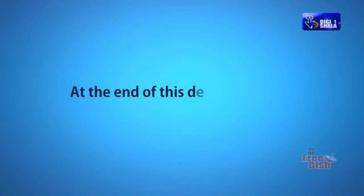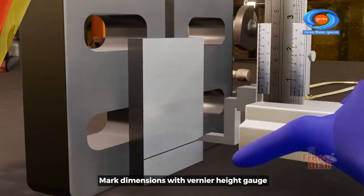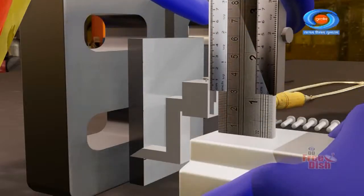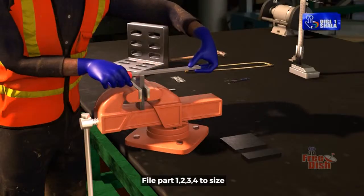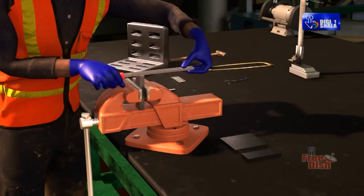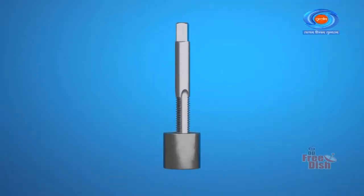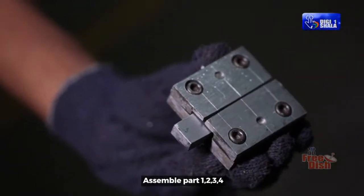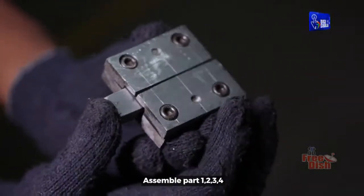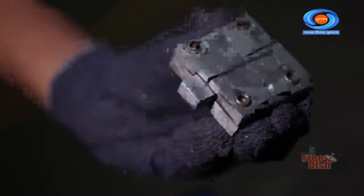At the end of this demonstration, you will be able to mark dimensions with a vernier height gauge, file parts 1, 2, 3, 4 to size, drill, ream and tap at the correct location, counterbore to the required depth, and assemble parts 1, 2, 3, 4 with dowel pins and cheese head screws.